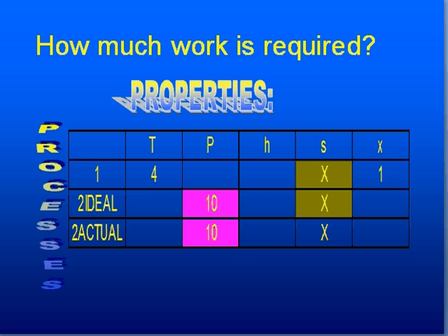We notice that in the case where it's ideal from 1 to state 2, the entropy is constant because we're treating it as reversible and adiabatic, so delta S equals 0. So notice you have two properties about state 1. You have the temperature and you have the quality, 100%. So you can calculate S. Knowing that S, you can get the S at state 2. That, along with the pressure, allows you to find the data for state 2. So we can calculate enthalpies at both state 1 and state 2.